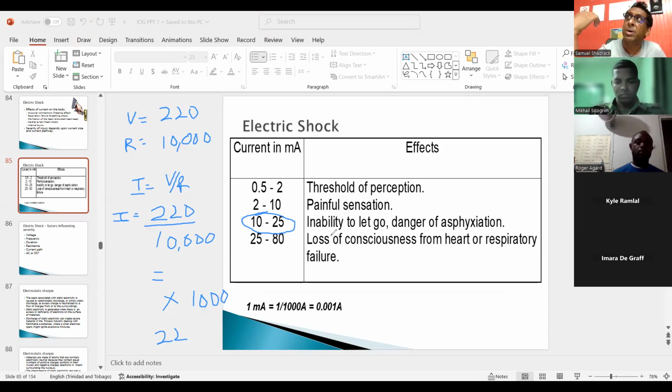So you could get the person away, but you have to use a non-conductor, like a broom with a wooden handle. If you ever get a PVC pipe or something, fine, you could get them away. But the longer they're there, the greater the effect on your heart, causing burns and of course disruption to your heartbeat and heart rhythm, which may result in death,